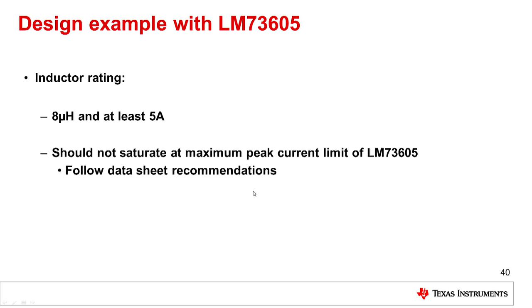So the inductor has to be an 8 microhenry inductor rated for at least 5 amps, and be sure that the inductor you select doesn't saturate at the peak current limit of the LM73605. And of course, you need to follow all the datasheet recommendations, as you normally would.